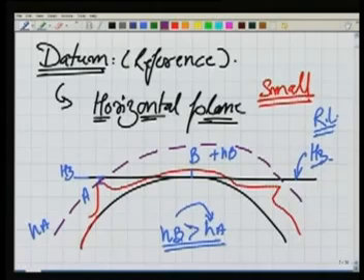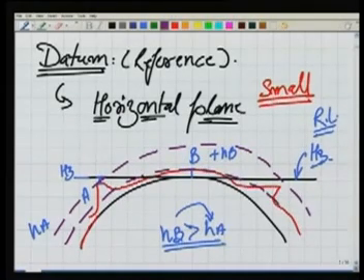Everywhere we say this as equipotential surface. Similarly, the gravity will be also same along a surface which passes through the point B, and both these, the one which is passing through A and the one which is passing through B, both are nearly parallel to the average curvature of the earth. Now what is the meaning of this? If the gravity is same all over, if I highlight this, all over this surface, the gravity is same, as well as it is same here.